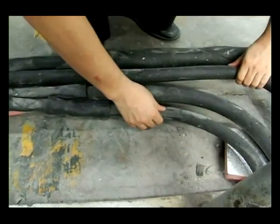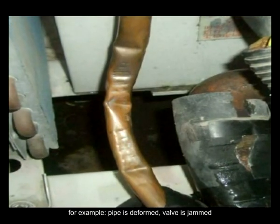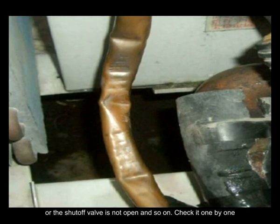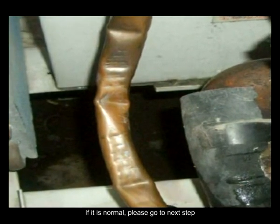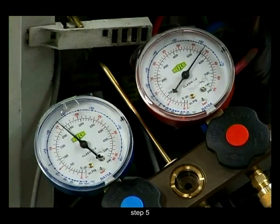Step 4. Check if the liquid side pipes are jammed. For example, pipe is deformed, valve is jammed, or the shutoff valve is not open, and so on. Check it one by one. If it is normal, please go to the next step. Step 5.